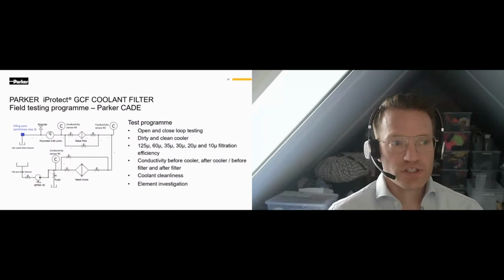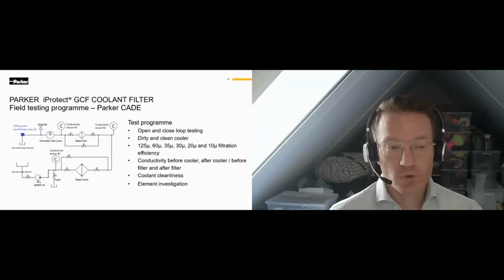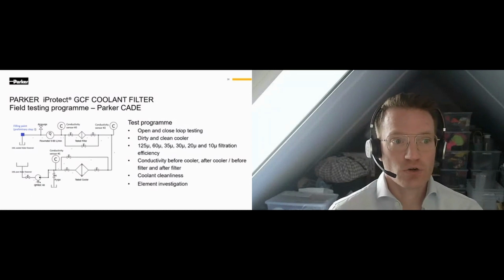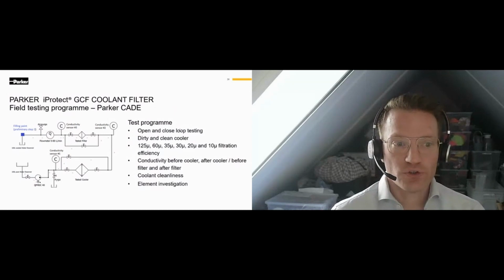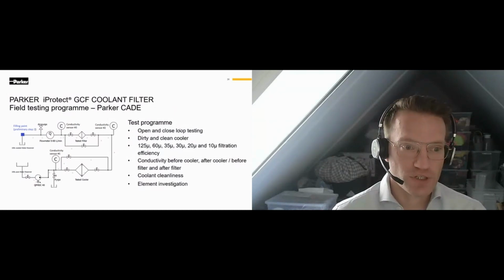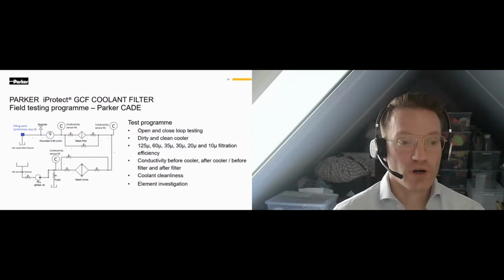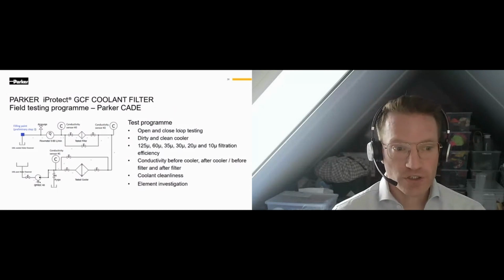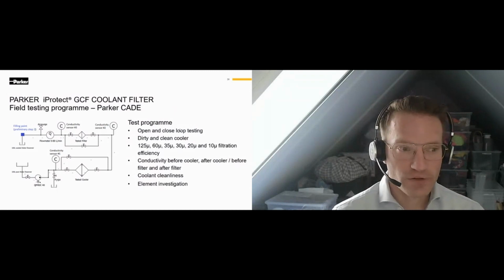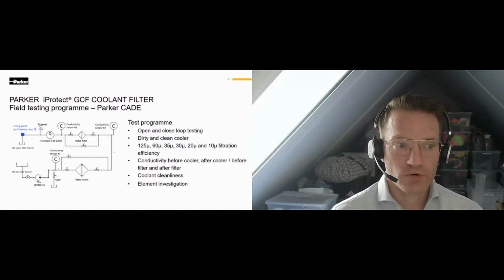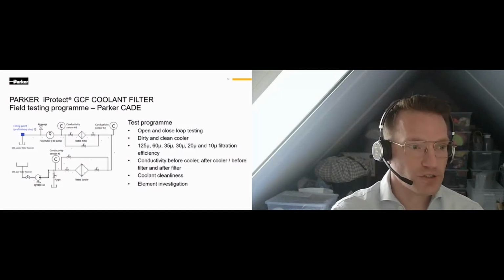So we're running some field testing at the moment with multiple customers, but we also do internal field testing with our colleagues at the Caddy division. We're testing multiple options of the coolant filter to determine the correct filtration media. We test the conductivity impact on the filter. Before the filter and after the filter, we're monitoring the coolant cleanliness, and we also examine the elements that are returned from the field to see what kind of contaminants are trapped in our filter elements. So that's ongoing at the moment.